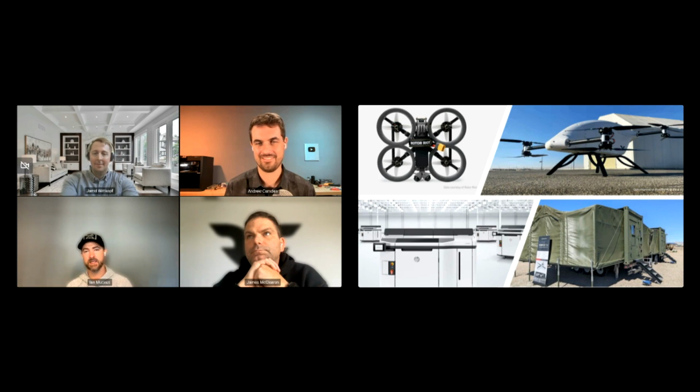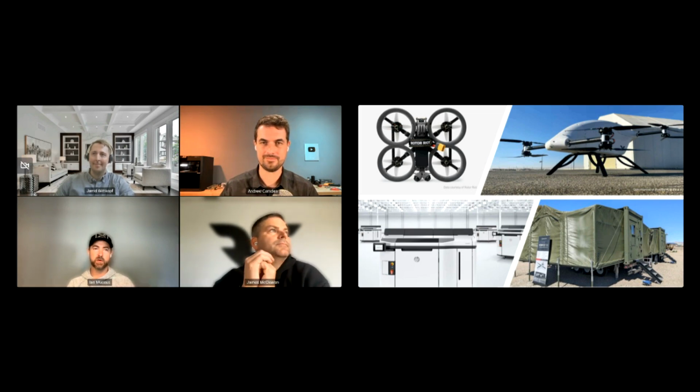And when you look at something like MJF, you have a process that is inherently very high detail. These effectively 2D inkjet heads, very small minimum voxel size, and what you can do with that, and the constraints that are released, is really special. And then when you're looking at whether you're going to de-risk this by printing some first parts, yeah, sure, in FDM, but sometimes you don't learn what the issues are going to be until you go to some of those processes that get you into those higher volumes. So we'll go to MJF right out of the gate.